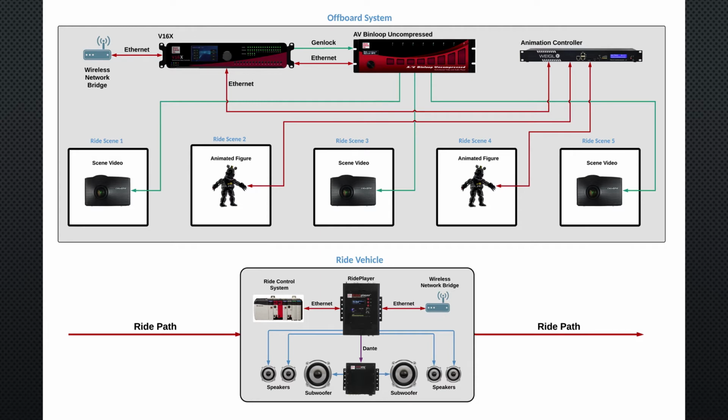This can be as simple as a single audio track for each scene, or it can be as complex as multiple animatronics, pieces of show action equipment, video tracks, audio files, and much more. The show controller will be the one distributing the messages to all these devices, or in some cases, subsystem controllers will help to distribute some of the messages, like audio or projection subsystems. These messages can come over a variety of industrial protocols like Ethernet IP, Modbus, and more. We're constantly working to add new methods of communication to the controllers.